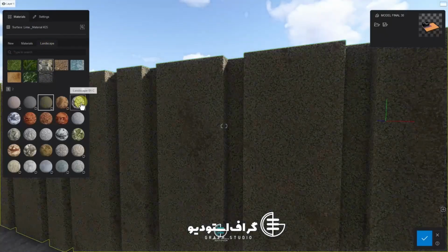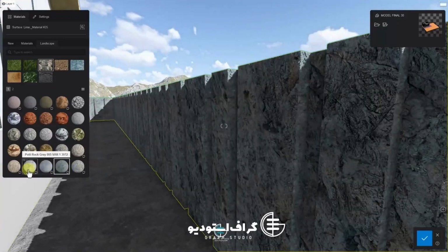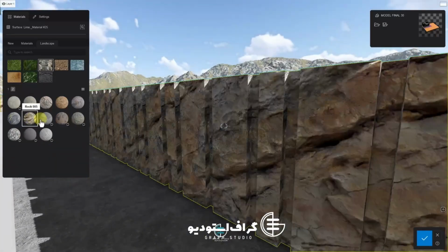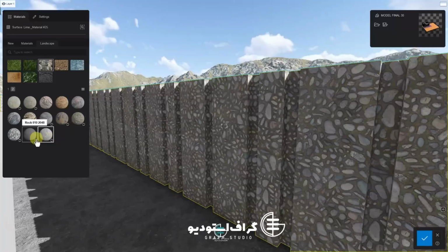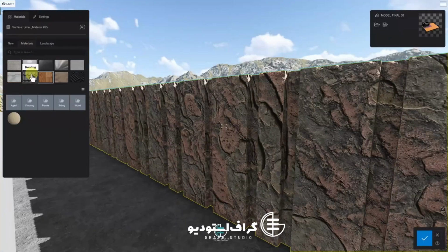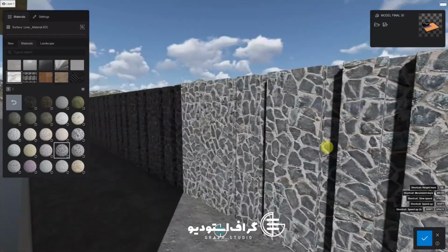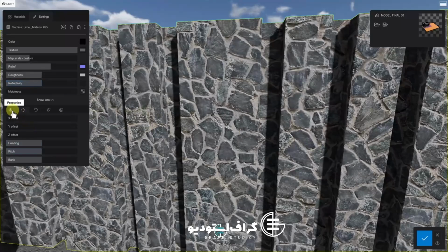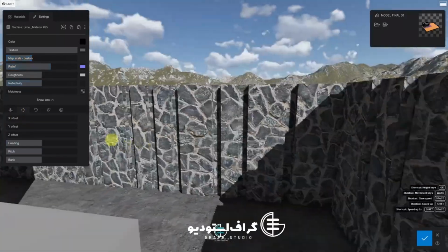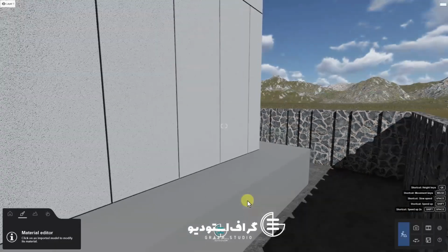I make the scale small, stronger bump, more matte roughness, like this. Let's see if we can add grooves to it. We should use the stone materials, but not with this intensity. Since the new material is clean, I'll add a little. These grout lines make it look like we are adding AO ambient occlusion. Yes, look. If I increase it, close up. Yes, its presence is good. That's it. I can even copy it.